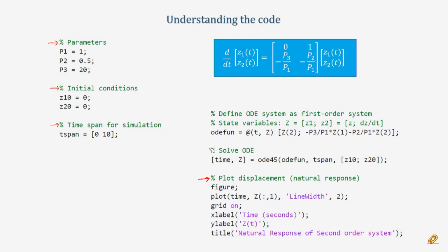now we will solve the differential equation. To solve it, we use ODE45. The syntax is first you write down the name of the differential equation, which was the name we gave to it. Then the amount of time for which you want to simulate, which was this, and then the initial condition, which was these. See, the initial conditions have been written in vector form. In MATLAB, when you write A semicolon B, this means in maths actually this.